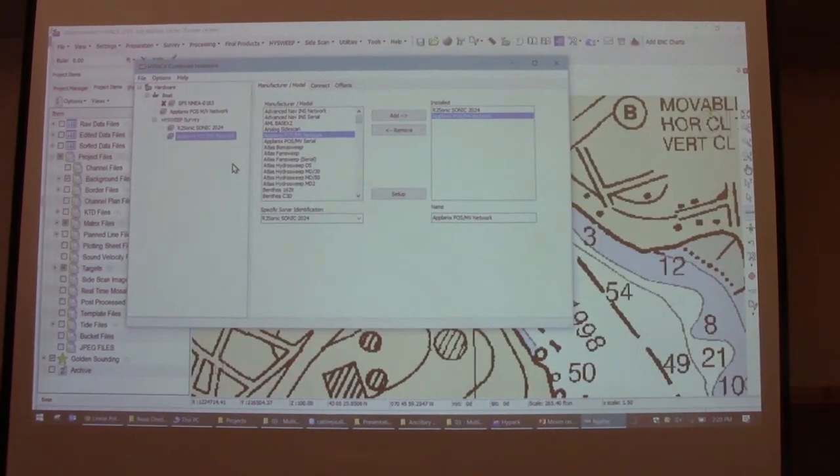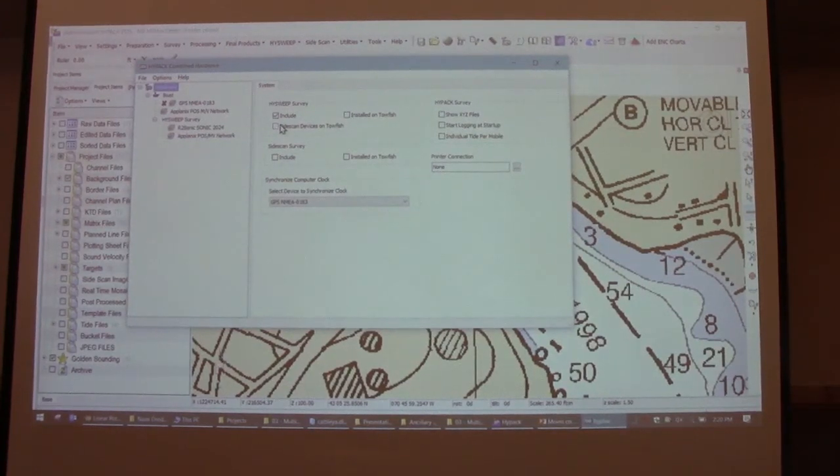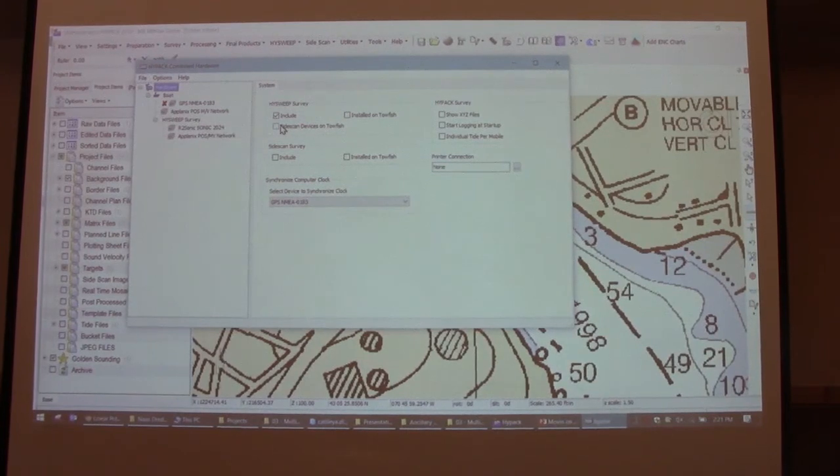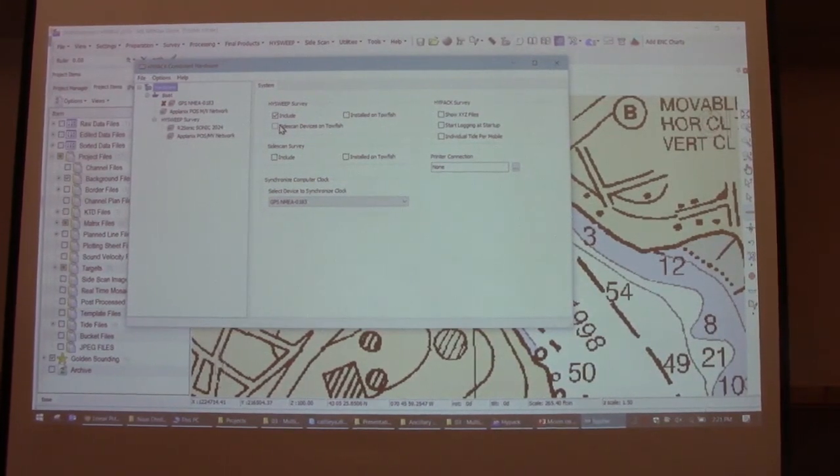And to further the answer to that, this is what happens on oil rigs and stuff offshore. To position those things, they'll put RTK GPS antennas on the 4 corners because they want to get the alignment just right so that they can anchor or spud down in place into the precise position.